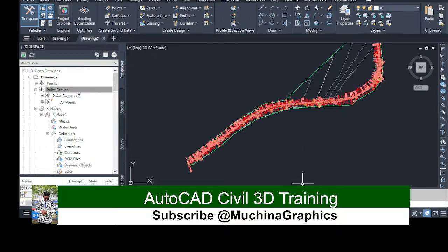But before that, I hope that you have been successful in creating the alignment. But if you're not successful, let me take you back again so that we can be on the same page. So you need to click alignment in your home tab, and you click alignment creation tool, and then you choose the type of alignment. You can name it here. You can also change some of the settings here. You can also change the design criteria. You can change the design speed, whatever the road that you are designing for.